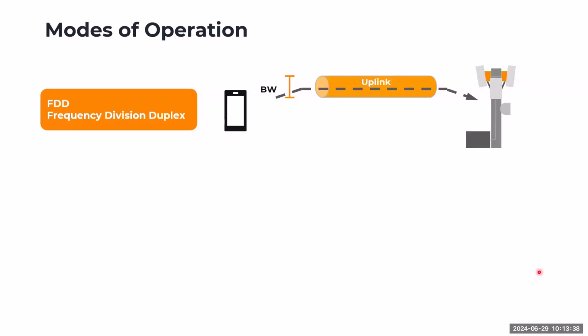It's the same concept with the satellite communications. So you have the uplink signal and the downlink signal. Anything that you transmit from your mobile phone going to your cell site, we call it the uplink. And the signal going from the cell site down to your UE, we call it the downlink. If this transmission is happening using different frequencies for uplink, different frequency for downlink, we call it the FDD, the frequency division duplex.